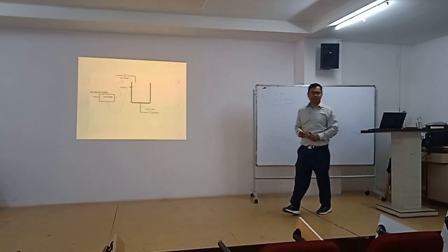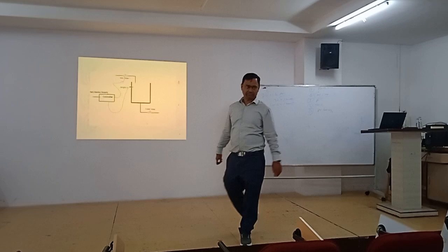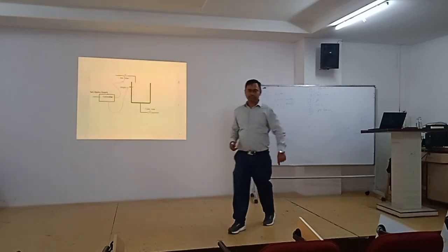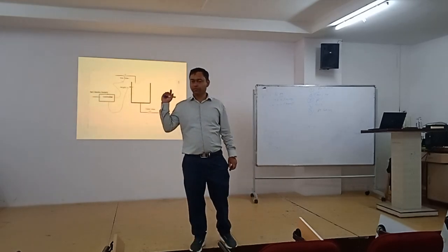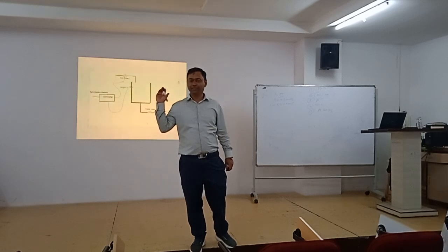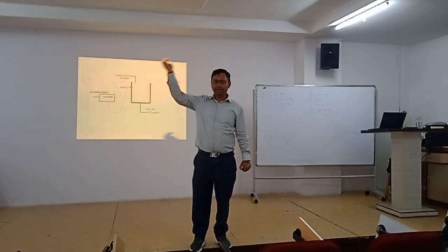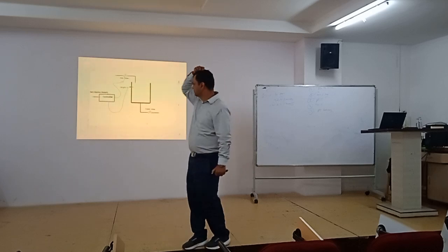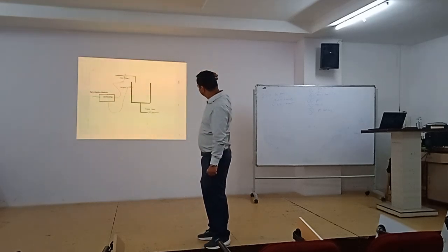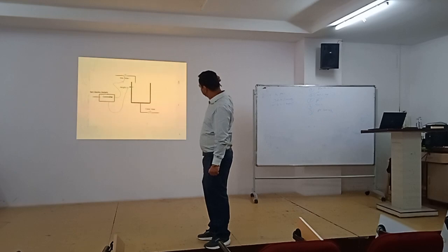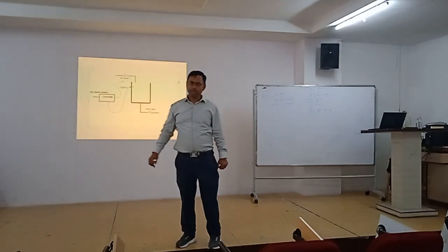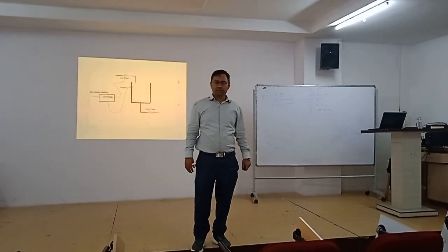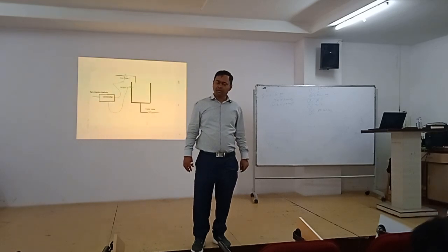There are some famous companies which are doing PC based controllers. Now, do they fully control? Still, it is open loop; we are discussing that point. I am saying it is partially closed loop, because we are not sensing the outlet valve, the rate at which the liquid is flowing. We are just opening and closing the valve, so it will take more time to fill.